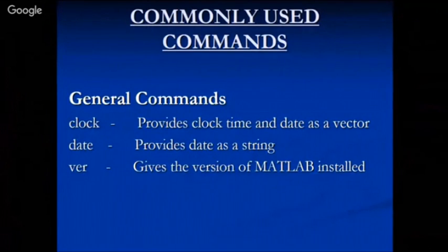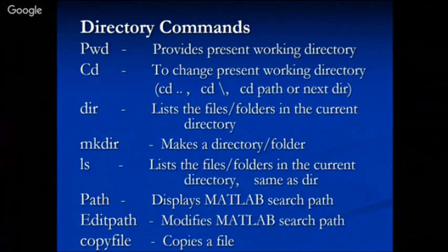Okay, so next is commonly used commands. Some of the commonly used is clock. When you write clock on the command window, that is the command prompt, automatically it will provide you the clock time and date as a vector. Date provides a string, and then ver, if you give it, gives you the version with which you are working. So this PPT I'll be giving you, and it will be there in my SlideShare also. So you can just go and work with it afterwards. Some of the things which are not much important, I'm just not writing. You can just try this.